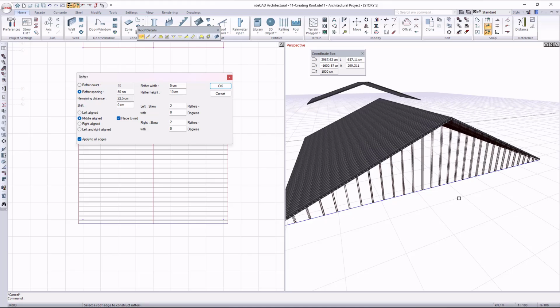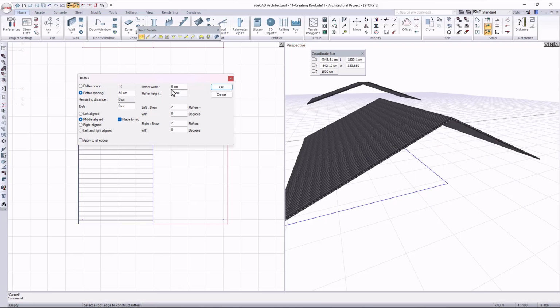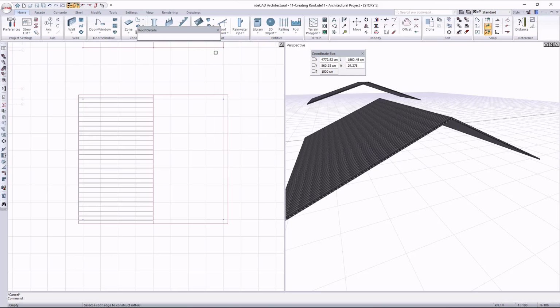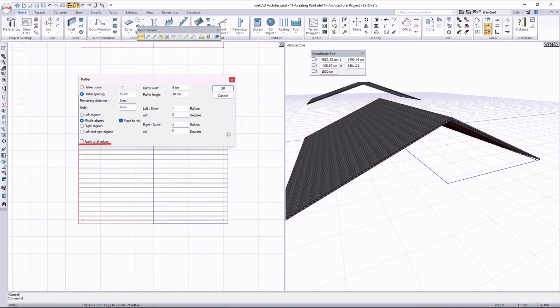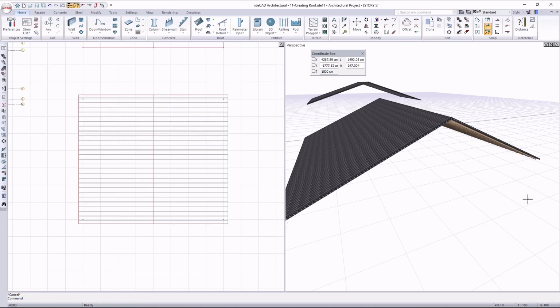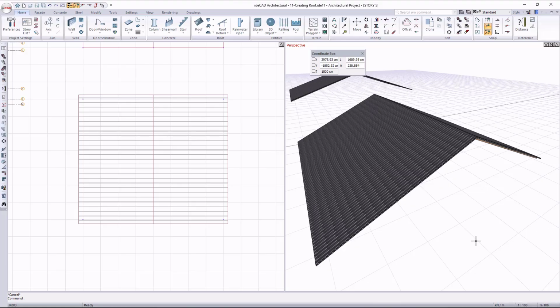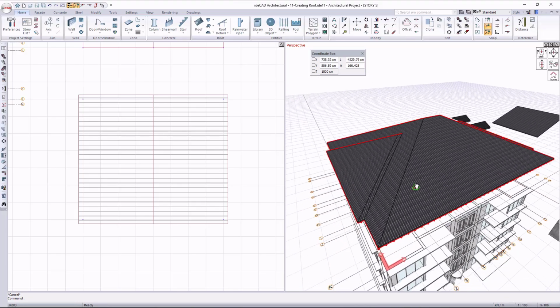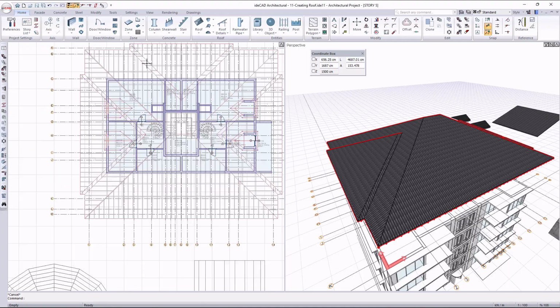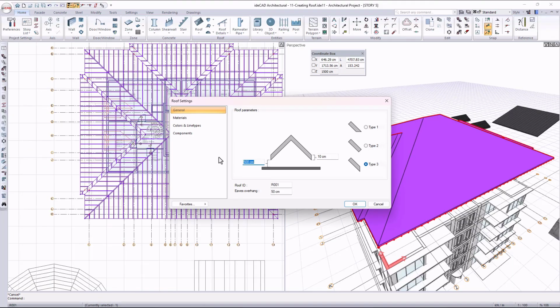To avoid such issues, when working with roofs that have been converted into gable roofs, the Apply to All Edges option should be disabled while adding roof details. Instead, each relevant eave surface should be selected individually. This way, the details are applied only to valid surfaces, ensuring that no errors occur in sections or elevations. The roof is now lowered back to its original elevation, level 0, and a gutter will be defined.